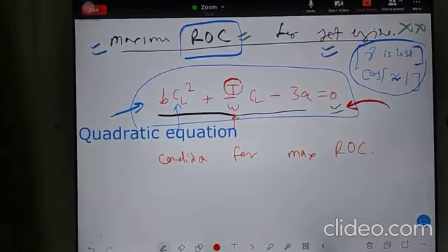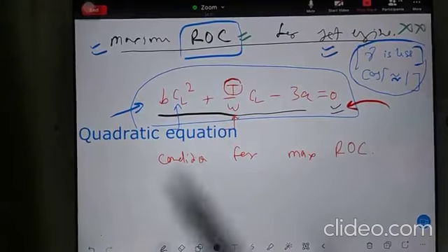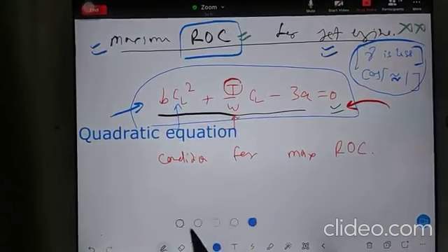So if it is quadratic, then you have two values of Cl. For that I have a numerical, that numerical I will give you. You can solve for both the values of Cl, and you can choose for which value of Cl you are getting maximum rate of climb. Because you got two values of Cl, right? So it is your choice to check.